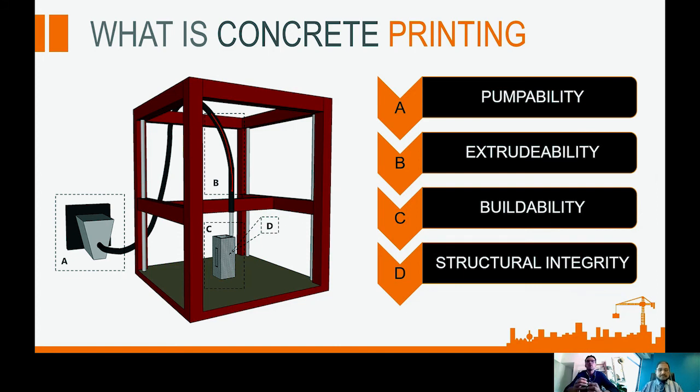If you take too long before you deposit the next filament, that would impair the interlayer bond capacity between the subsequently deposited filaments. And things can then delaminate between the 2 layers, I take it? Absolutely. This is something that we call constructability optimization that I'll touch on in my next presentation. Okay, perfect.